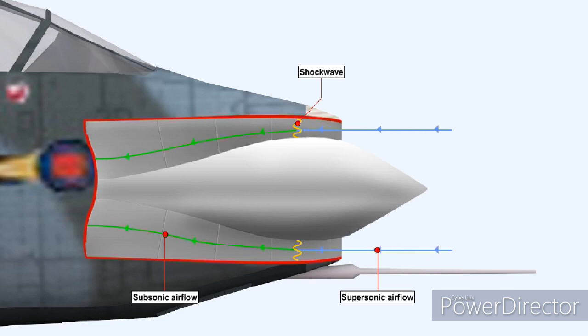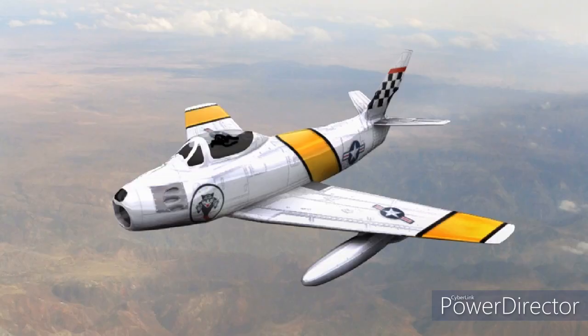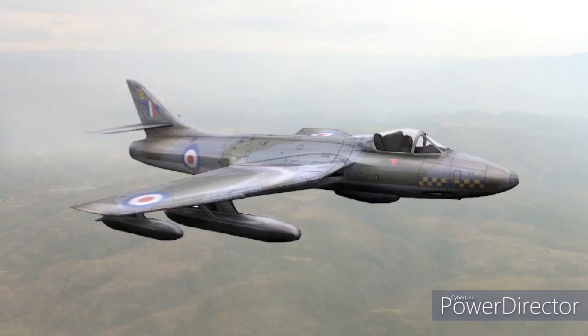One important characteristic of a shock wave is that air flowing through it will be slowed. The task of controlling the shock waves that form on or in the air intake, which is fundamental if we're to efficiently reduce the velocity of the airflow, is undertaken by a supersonic diffuser. The supersonic diffuser can be quite simple or quite complex, depending on a number of factors, among which is included the supersonic speed range of the aircraft. For instance, many jet fighters are not designed for sustained supersonic flight, and can therefore use quite a simple intake diffuser.